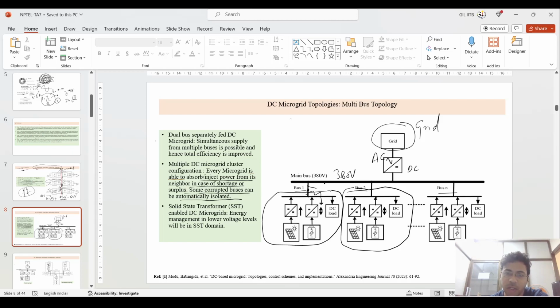That is the main point, because the main bus bar has to maintain 380 volt, because from here you should give power to this grid. So the inverter, which you have used for the DC to AC conversion, has to maintain certain specified limits such that it maintains this 380 volt. It should convert to 230 volt, or 314 volt line to line, if you want to convert.